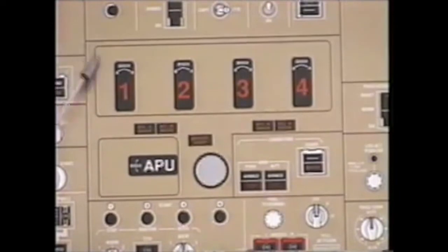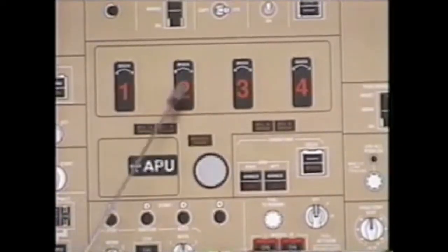Continuing the review with the fire control panel, which includes fire indications for the engines, the APU, and lower cargo, forward and aft. Please note that the APU fire control handle has a red light as the engines do. Immediate action for engine fire, severe damage, or separation is to now call for the QRC for that condition. The immediate action for APU fire warning is again to call for the QRC for that condition. And immediate action for lower cargo fire warning is to now call for the QRC for that condition.